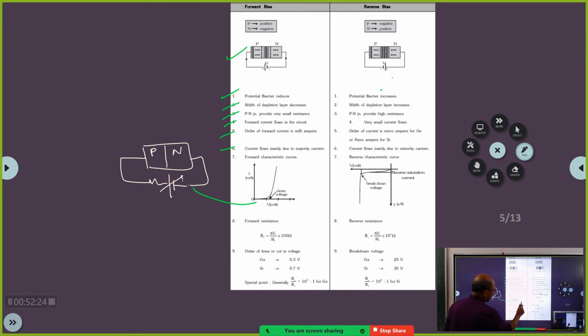So this voltage here they have written as VD. VD is what? This voltage. And ID is what? This current. And here they have written it as IF. IF means forward current. Now, as you increase this voltage, the current will slowly increase. After this point, the current will increase like this. Did you observe this?